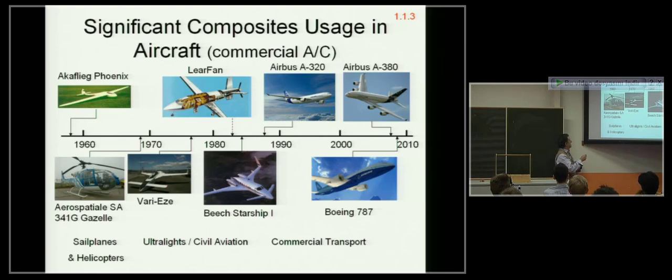The blades in a helicopter can be approximated as beams. So what is simpler than beam theory? Well, first of all, it's very large deflections. It's not just our standard Bernoulli-Euler beam. Second of all, it's very large rotations. If you put a camera at the root of a blade and you see what happens to the blade as it rotates, it's exactly like macaroni. You won't believe how much it flaps and rotates and twists.